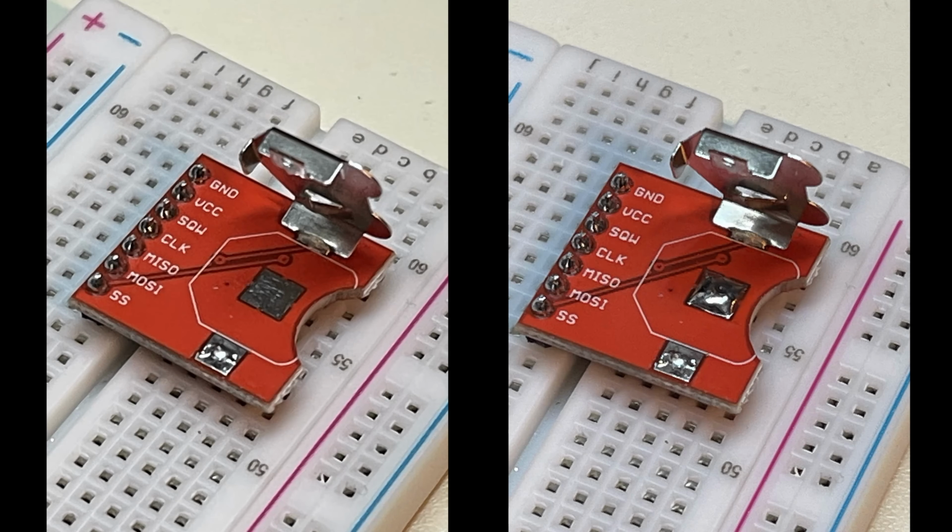After I recorded the video portion that you just watched, I was going back and doing a little work with my digital multimeter on this PCB. On the bottom side is the IC, that is the real-time clock IC. And then on the top, the part that I'm showing here is where the battery would slide in. And I was ohming out the connection and just making sure everything connected from where the battery is held to the IC pins, and that all ohmed out fine. But when I would actually slide a coin cell battery in, I was not getting my voltage all the way to the IC. It was just not coming through.